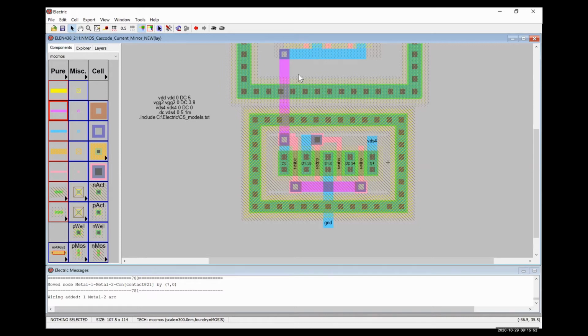Dr. Hartman, can you remind me why the ring around both transistors? I'm sorry, Diego, I'm having a little bit of trouble hearing you. Could you remind me what's the use for the ring around both MOSFETs? Sure. So this bottommost ring, as we can see, it's tied to ground. And so what this ring is doing is it's serving as the connection to the body for all of these NMOS transistors down here.